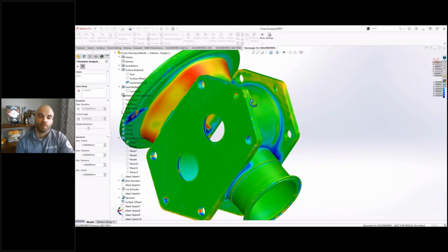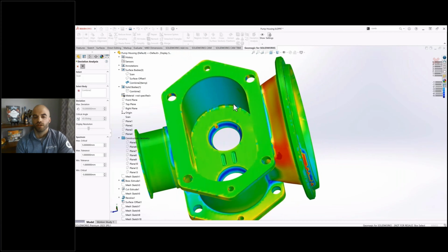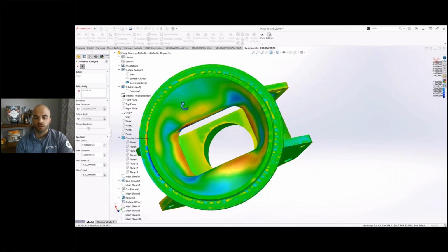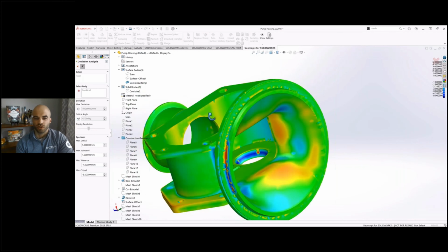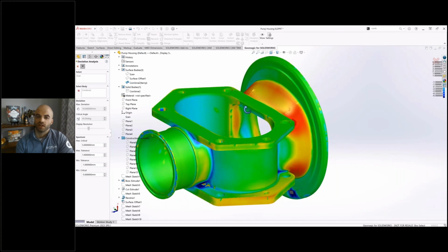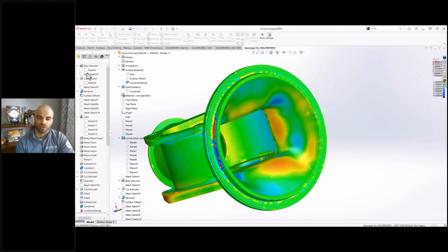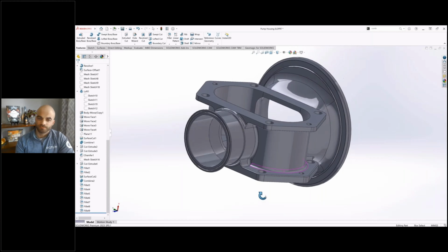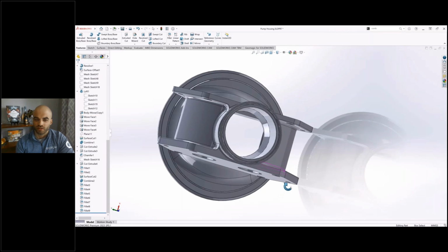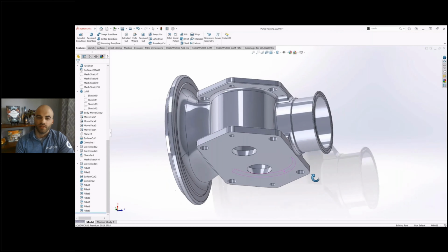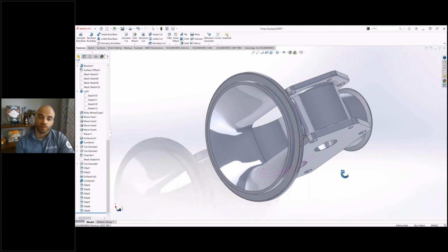We have to be one way or the other. This is the price we pay for getting a cleaner model with an offset surface, as opposed to a second loft, which would be, if you're trying to do any kind of edits, that second loft is going to be such a pain in the butt unless you do a lot of work to link it parametrically to the first, which is almost the same thing as doing the offset, just more steps. And the inside, we were able to get rid of those red spots much nicer.